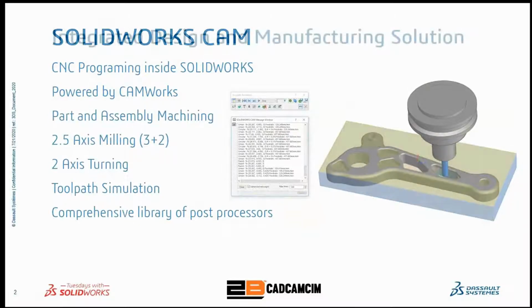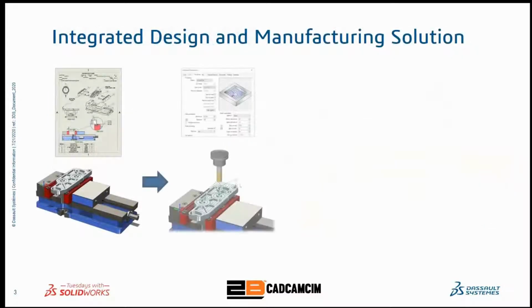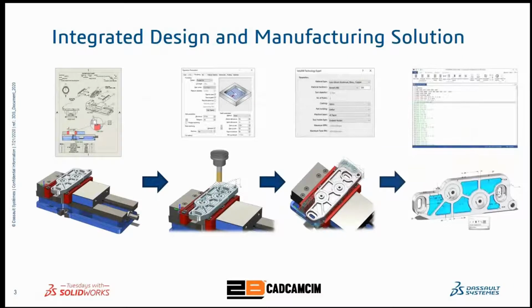So in this webinar, I am going to talk about 4 sections mainly. We are going to discuss the process to complete and fine-tune your machining process in 4 sections. The first section is about the fixture setup, and we are going to talk about a fixture method, which is the vice, and how I can apply it virtually to hold my part to avoid any collision between the vice and the tool.